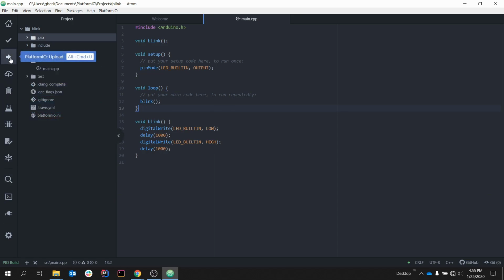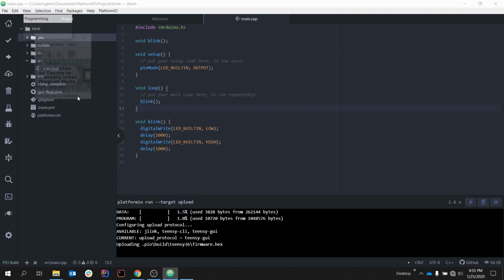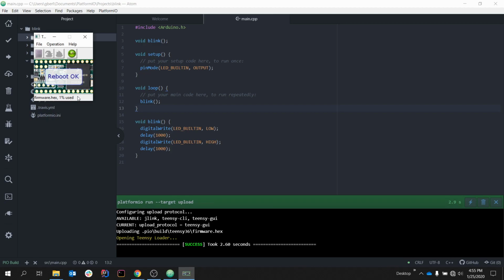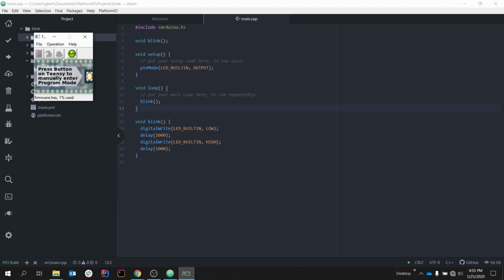But here, the upload, which is the same as the Arduino upload, you do need the board plugged in. Now the nice thing here is, as I mentioned, it automatically downloaded Teensy Arduino for me. I didn't need to download that separately. It set it up. The other nice thing is I didn't need to tell it which COM port I was connected to. I just plugged it in. It looked for the appropriate board serial or board ID through the different COM ports, and it selected one.